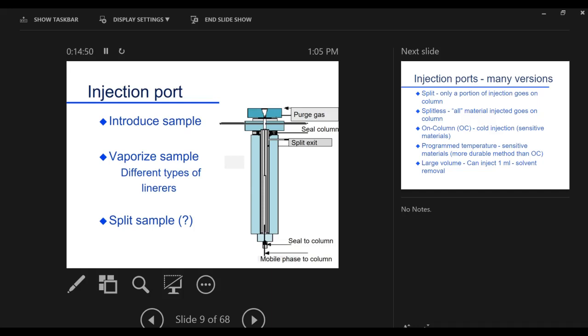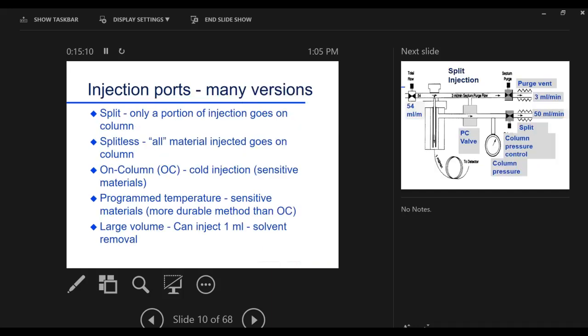So you make an injection, you take your syringe, you pierce this, you put it down here, we've got our gas flowing down here, you make your injection, it expands, and your analyte starts being swept down here. Some portion goes into this little column, the rest of it goes out this direction. So fairly simple system. It's interesting, probably 80% of our problems happen in that simple little system of things being clean, not being looked after.